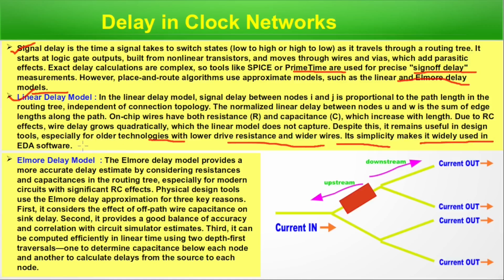Although it's a linear model, when RC comes into play, the wire delay grows quadratically, and we are trying to model it through the linear delay model. It's not appropriate, although it's a good assumption because it's a simple model and it's very useful for older technologies